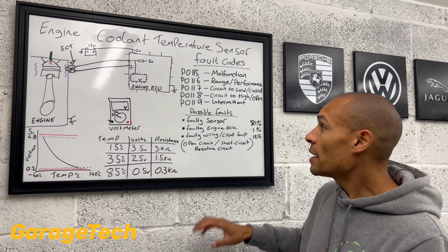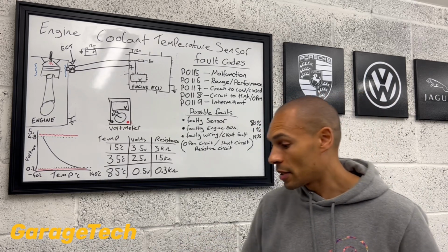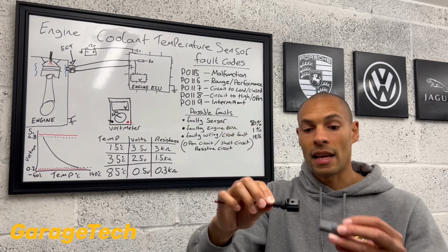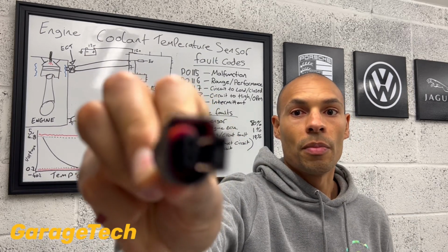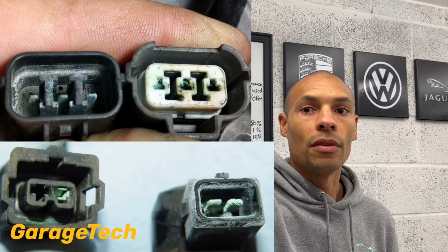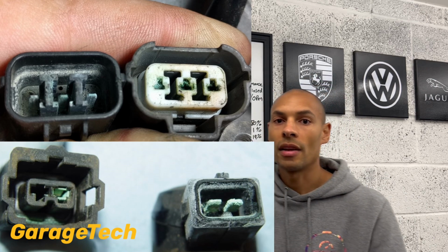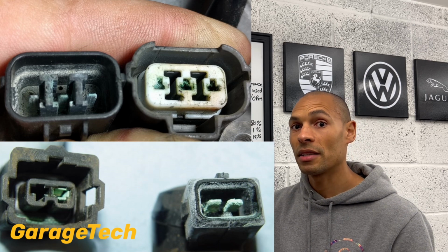So with any of this, before you start going mad and doing loads of bits and pieces, I'd say check the plug. The plug will look something similar to that. It connects onto the coolant temperature sensor. Check inside the plug to make sure you can't see any corrosion, or that the pins are all intact inside there. Have a visual inspection of the wiring as best that you can.